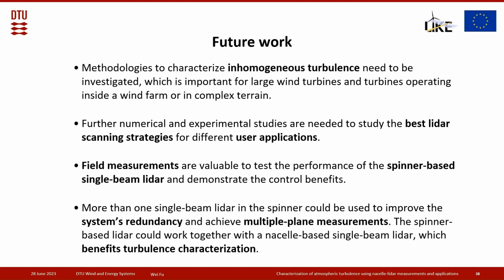Further numerical and experimental studies are needed to test the best LiDAR scanning strategy for different user applications. Just like I said, it depends on which parameter is most important for you. The LiDAR scanning pattern also depends on how large your turbine is. Thirdly, field measurements are valuable to test the performance of the spinner-based single-beam LiDAR and demonstrate the control benefits.